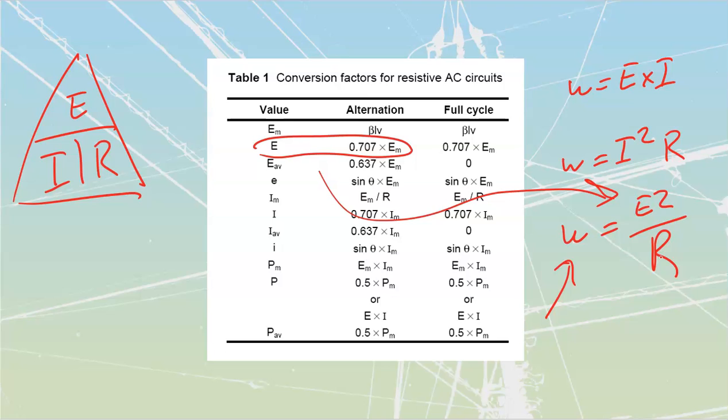Go through your self-tests. Make sure that you're getting all of those values. If you're not getting those values, go back through until you find out where you've gone wrong. Be very careful. Always identify whether you're looking at an average, RMS, effective, peak, whatever that is going to be, and that you're using the correct formula for that.